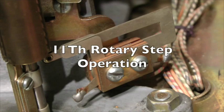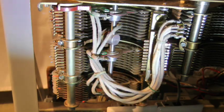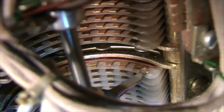Now let's take a look at the 11th rotary step operation. Here we're going to see the line finder vertically step and then rotary step as on any normal dial tone request. However, after it reaches the 10th rotary position, it still hasn't detected battery on any of the sleeve terminals, so the F or B and F relays don't operate to stop rotary stepping. Line finder rotary steps one more time to the 11th rotary position.